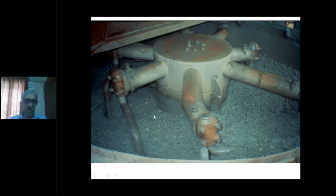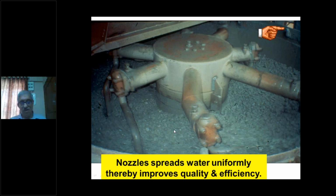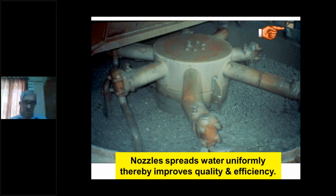And the mixers are so designed there is enough airspace inside, so mixing is very efficient, and you get 1 cubic meter in a batching mixing plant which produces 6 cubic meters per hour. So 1 cubic meter per minute: 30 seconds for batching and 30 seconds for mixing. So nozzles spread water uniformly, thereby improving the quality and efficiency of the concrete mixer.